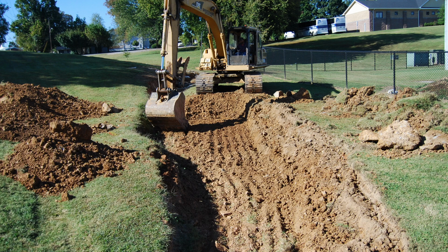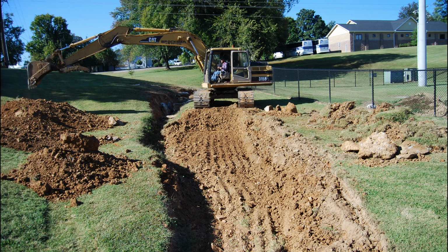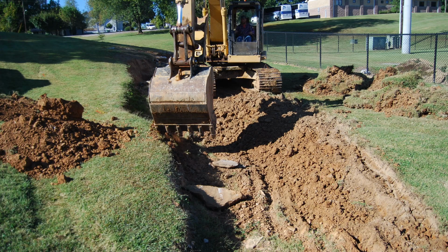Here we're making a much wider floodplain that is level in cross-section so that the water will flow in a sheet-like pattern, saturating the soil and creating conditions for wet meadow wetlands to develop. We temporarily piled the soil on higher ground and would later spread it to blend in with the surrounding landscape. The excavator dug down to limestone bedrock along the entire length of the stream.